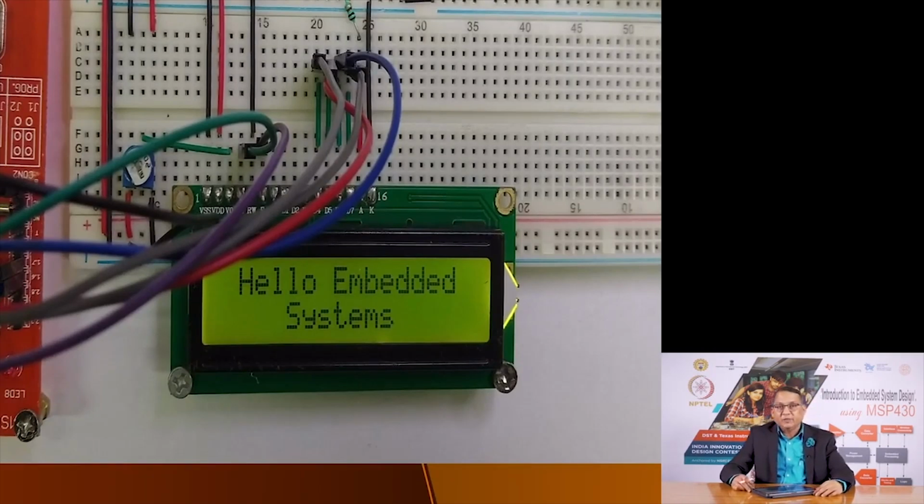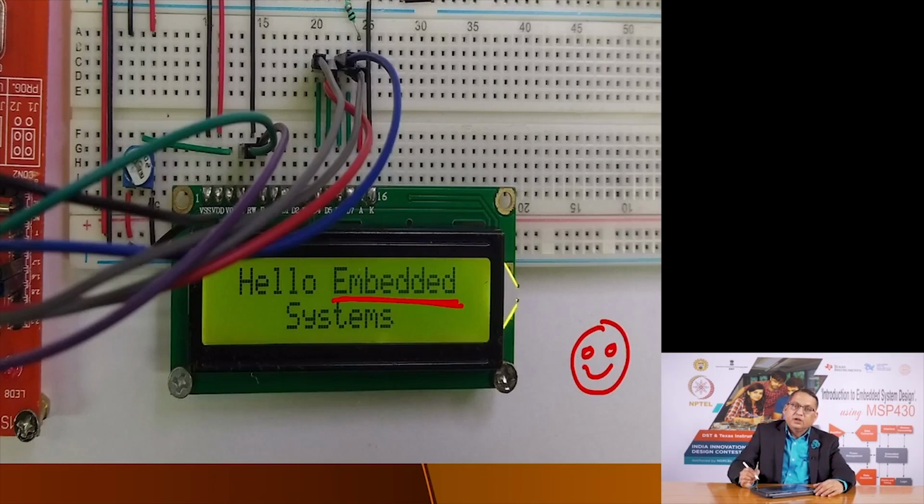Now the LCD is capable of creating custom characters also. These are all built-in ASCII characters that it is able to print. But what if you wanted to print a smiley, something like this, or a heart, something like this? It is possible to print the heart like this by creating a pixel character and storing this information in the RAM that the LCD has, and then invoking them so that you can print these characters.